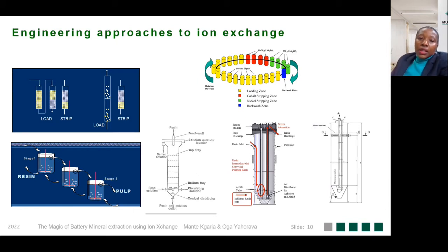On a commercial scale, one can use a range of processing vessels as ion exchange contactors. The various processing vessels have their own strengths depending on the application. For example, fixed bed ion exchange can be used for dilute clear solutions, where the fixed bed can be operated in downflow and achieve higher volumetric throughput. For difficult to filter solutions, resin in pulp can be used to minimize metal losses due to entrained solution to the tails. For more complex separations, ISEP contactors can also be used.